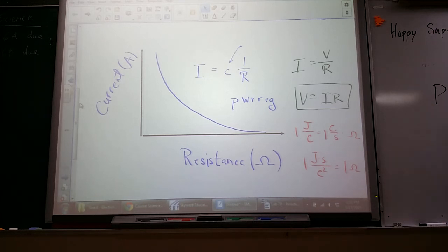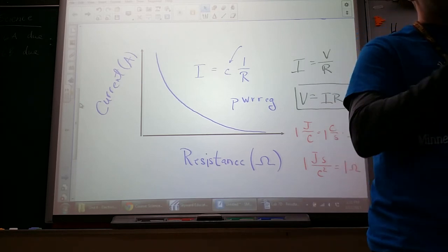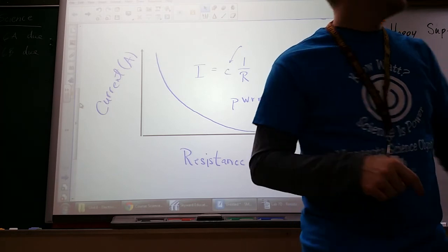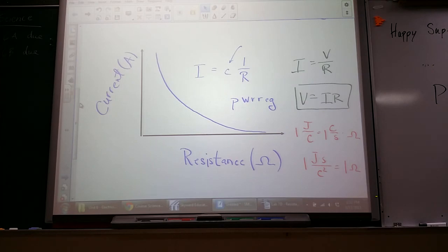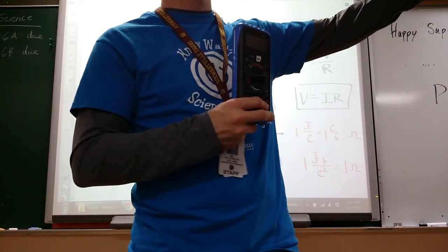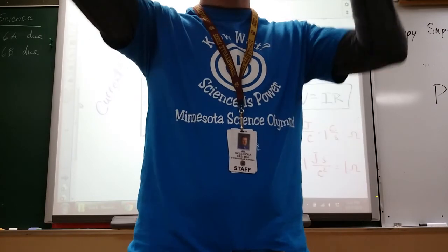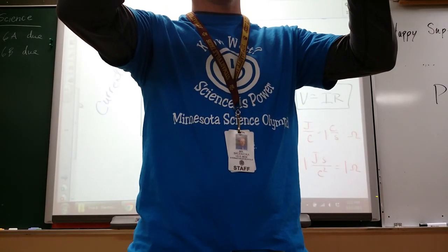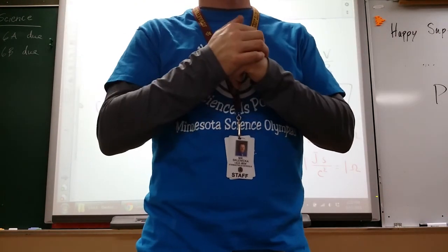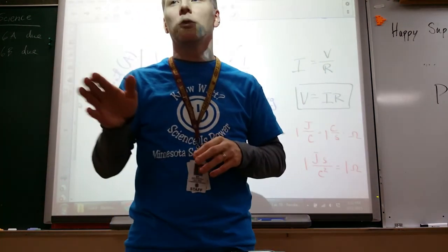You're going to make wires out of these, and the way I want you to measure is actually different from what's in the lab, because I guess I didn't review that lab well enough before I printed it. It works better to use a multimeter in this lab and just have the multimeter measure resistance. So you'll pick the two ports appropriate, use some of the probe wires up on the left door, and then you can just take those probes, insert them into the Play-Doh wire you made, and measure the resistance between the two points. It's a lot easier than the Ohm's law method that is detailed in the lab. So don't use that. That's a good way to do it, but this way works a fair bit more smoothly.